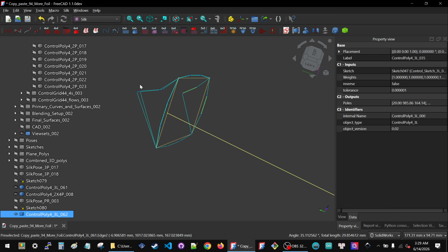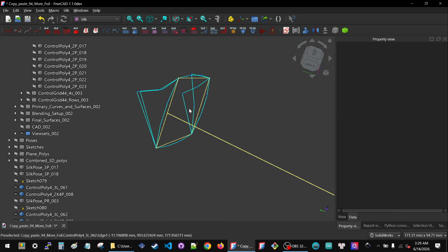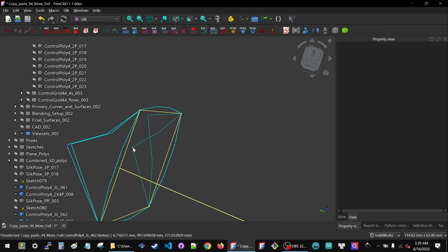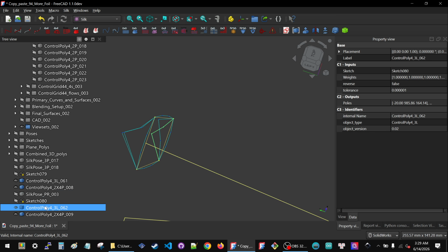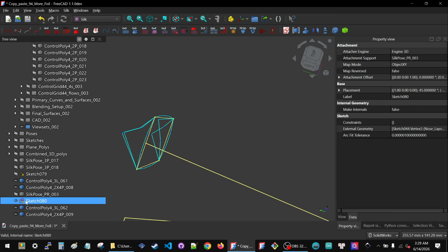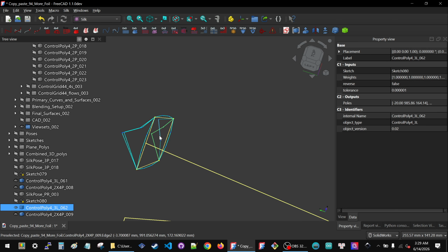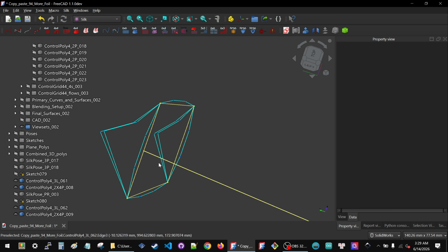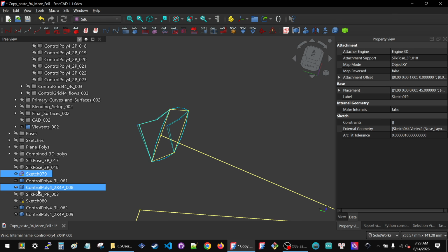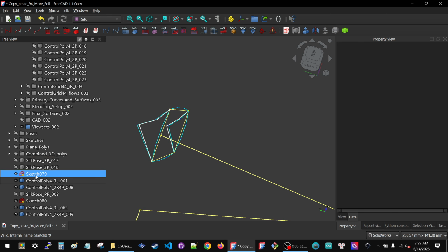Now let's see, is it going to match the elevations or is it going to get flipped? It's going to get flipped, and this is what it means to be flipped. It has applied this height over to this point and this height over to this point. That means that I drew this sketch backwards, but I don't have to redraw the sketch. You could, but you don't have to. You just take the polygon and you reverse it. Now it internally runs in the same direction as the base curve, and so the Z values match. Okay, so we have good height matching on both of them.